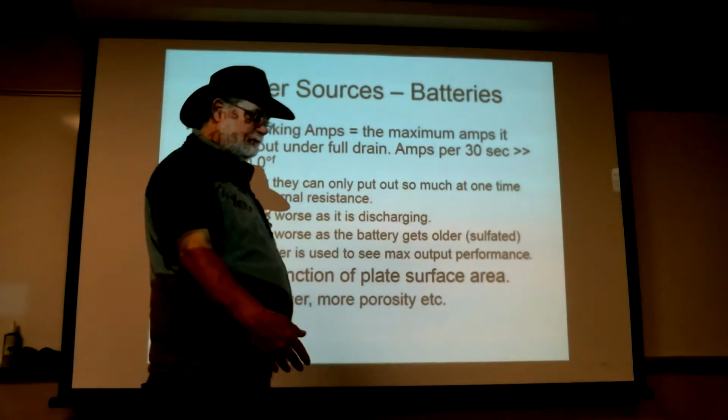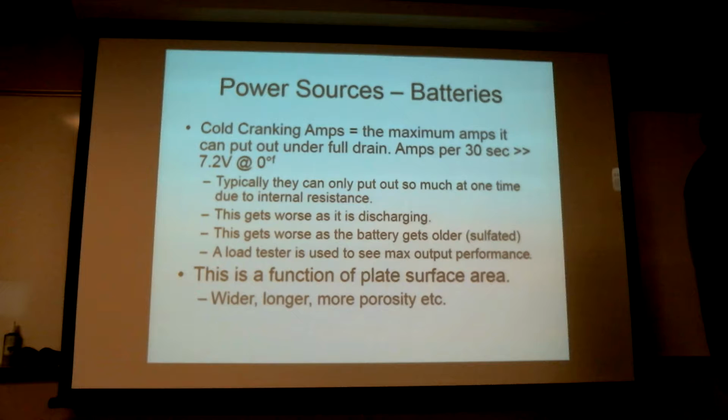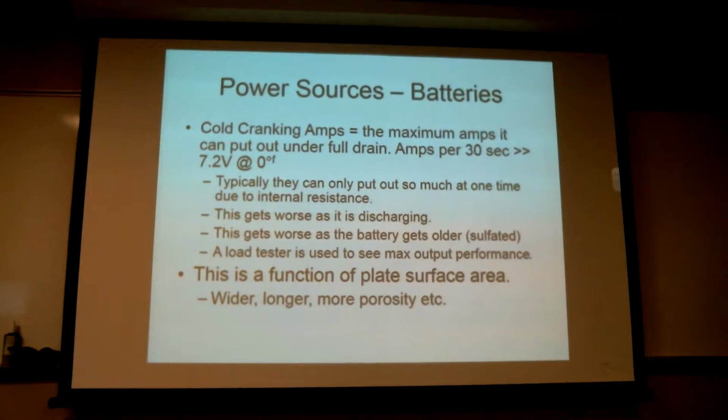Okay, so I get a battery. It's here. Pull out the electrolyte, look at it, hydrometer. Oh, it's pretty discharged. Now, one of you guys had yucky dark charcoal stuff in the fluid, right? That's probably a cell that's been charring and burning a little bit. That would be another data point. On the other hand, you pull it up, all the fluid's good, electrolyte says it's discharged a little bit. Logbooks say it's about 4.5, 5 years old. Throw it on the charger. Charge that puppy up overnight. It'll look really good. Hydrometer reading's really good. 12.9 volts. It's really, really good.